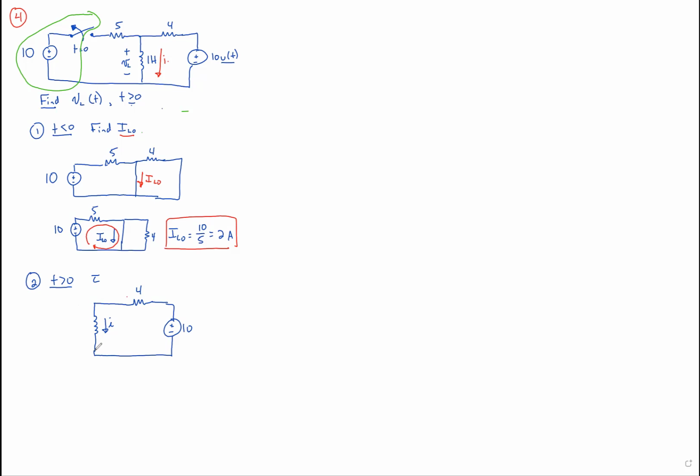And when we want to find impedances, the impedance that this inductor sees, we zero all of our independent sources. So the question is, from the inductor standpoint, we're not opening the inductor, but we're asking if we're forcing current through this thing and sucking it out of here, how much impedance do we see?